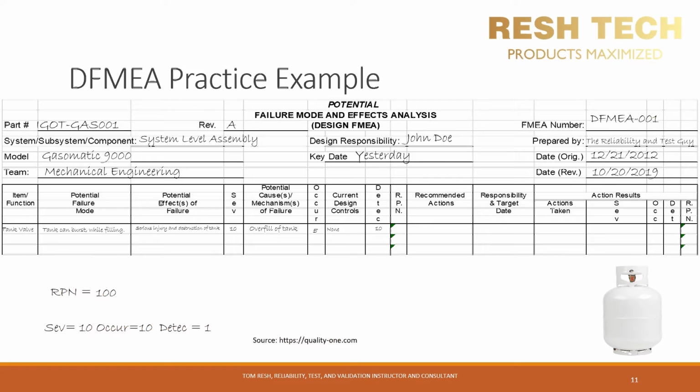Honestly, with a severity of 1, even with an occurrence and detection of 10, this failure mode would end up at the bottom of my bucket of priority action items, as it is a failure mode that will not impact the customer, let alone the customer will never even know that it occurred.